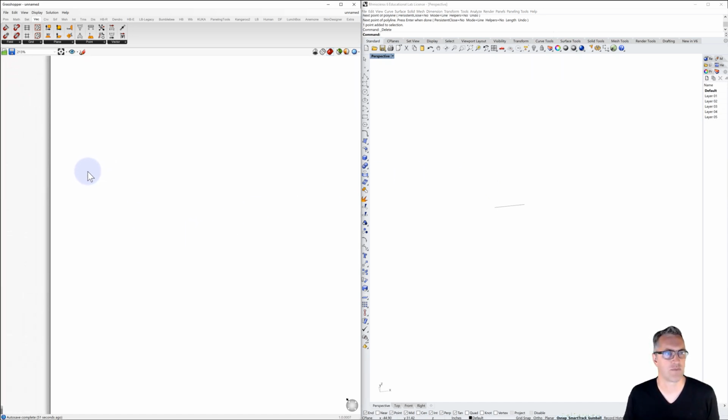So let's start by capturing the curve. And so we'll use a curve container, and we'll set one curve, and we'll select it. So now we have it. We can even hide this within Rhino, and we just see the Grasshopper representation.